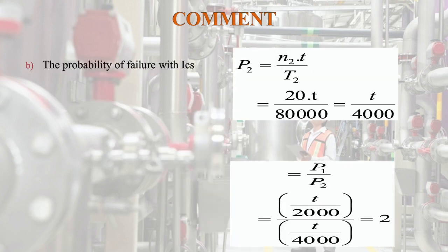Then the probability of failure with ICs is P2 equal to N2 into T by T2, that is equal to 20 T by 80,000, that is equal to T by 4,000. So the reliability improvement factor is equal to P1 by P2, that is equal to T by 2000 divided by T by 4000, that is equal to 2.